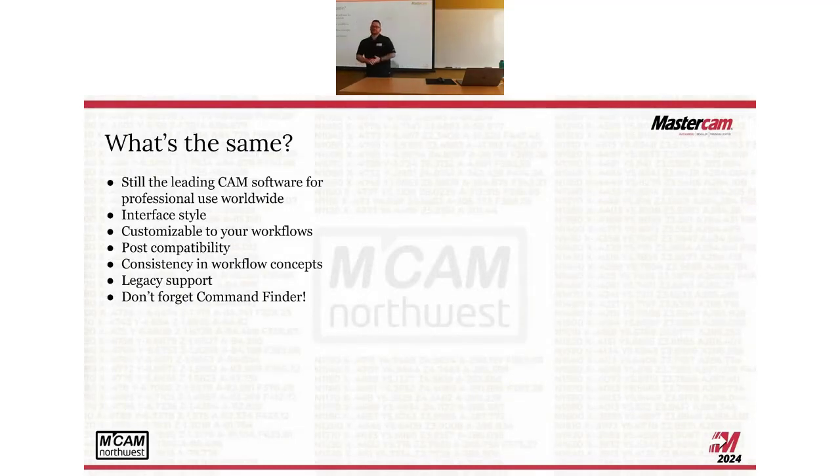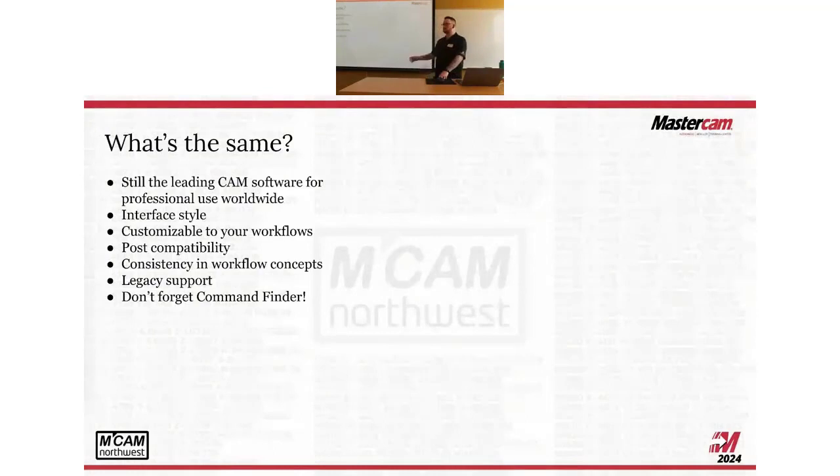Legacy support. So if you really want to use the wireframe toolpaths for some reason, or you have a real need to use something that's from a very old version that isn't even in the main interface anymore, you still have the option to do so. You can right click in your toolpaths manager and you can access that function. There's hardly anything that is truly gone.